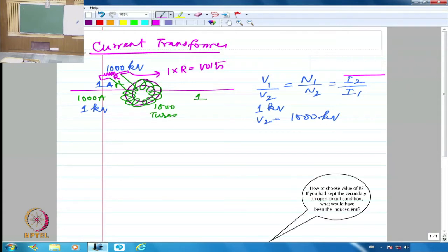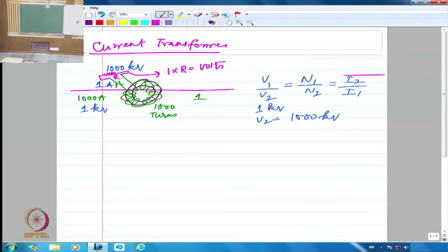Yes. In the secondary coil, the voltage will be 1000 kilovolt, and the current is 1 ampere, but if we have a low resistance. Low resistance is as good as a short circuit. I am going to have literally 1 ohm or 0.1 ohm or whatever. Low resistance is again compared to the base impedance. You will compare it with the base impedance, and compared to the base impedance it should be 1000th or 1/10,000th or something like that. So, it is as good as a short circuit.